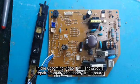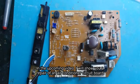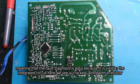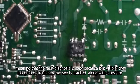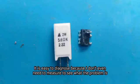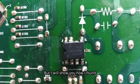In the upcoming video, I will show you a repair of an air conditioner circuit board, meaning that the fault diagnosis is easy because it is visible. The integrated circuit here we see is cracked along with a resistor. It is easy to diagnose because I don't even need to measure to see what the problem is. But I will show you how I found it.